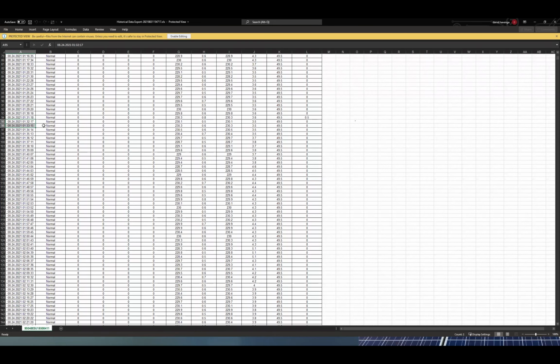The only time you'll see 5-minute data is if you have Wi-Fi issues on your site. So all of our inverters do store breakpoint data, so for up to 1 week. And that breakpoint data is then sent to the SEMS portal when the device connects back to the internet. But it's only 5-minute data intervals. So when you see you only have 5-minute data intervals available, that would be historic data that the inverter sent. So it wasn't live data that the inverter sent to the SEMS portal.